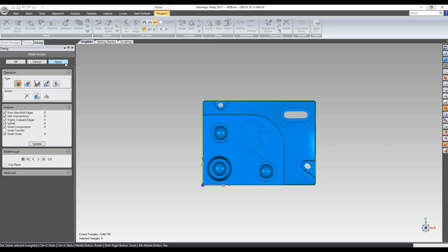This is important because you are not able to use auto surfaces for an assembly constraint. In Design X, we will be modeling parametrically. Then we will run a full history tree live transfer into a CAD package. By transferring the model's history tree, you are then allowed to make design changes in your CAD software.